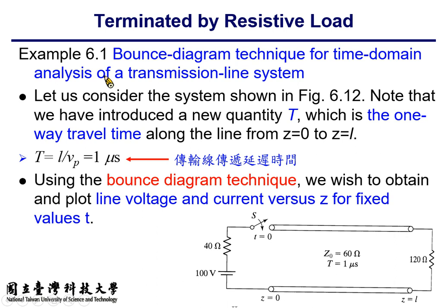只要你是 coaxial cable 或者是 microstrip line，那个距离就会比较短，因为跑得比较慢。All right, so in this problem, we describe the transmission line length in terms of propagation delay, which means that the signal going from left to right will take 1 microsecond. And the load impedance is 120 ohm.